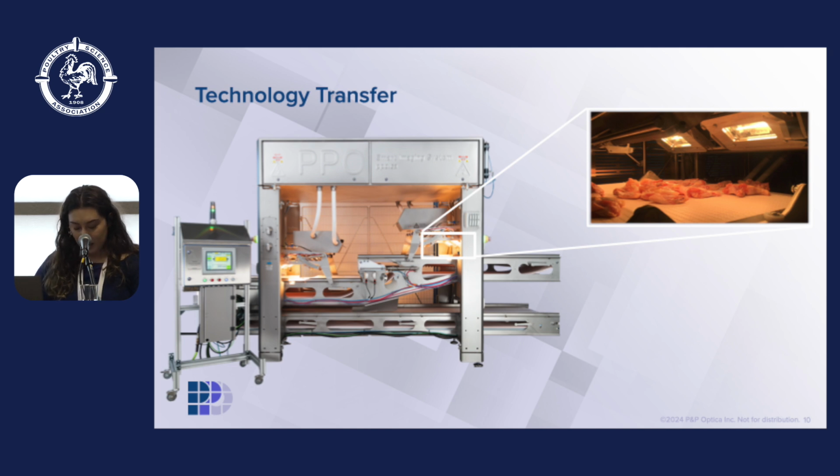So, kind of my shameless plug, on this slide is an image of our machinery that we've developed that is successfully performing NIR hyperspectral imaging in both primary and ready-to-eat plants. It has been designed to operate at speeds up to 120 feet per minute and handle up to 60,000 pounds an hour depending on the application. The operating temperatures range from 32 to 50 degrees Fahrenheit with a maximum relative humidity of 90%. It is IP69K or equivalent compliant, and it seals on all of the enclosures that we use. It's not hermetically sealed, but there is no direct exchange between environmental air and enclosure air. We have a cabinet dryer to make sure that any change in air between the two systems is dry, as well as a chiller to maintain internal temperatures for machine production.